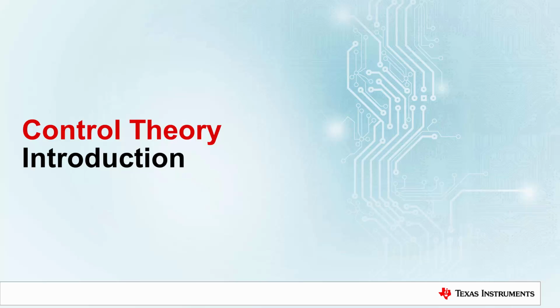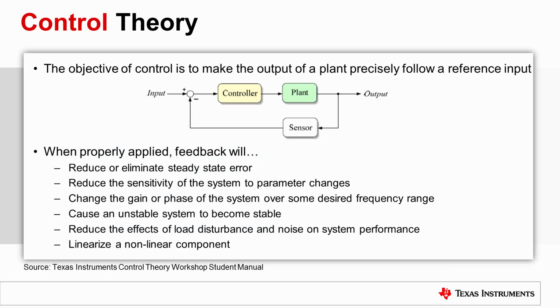Modules 1 through 3 have focused on power electronics and the physics behind linear regulators, buck converters, and boost converters. In this module, we will introduce the control systems that govern these power converters. Module 3 includes a deep dive on the buck converter, which derived the output voltage being equal to the input voltage times the duty cycle.